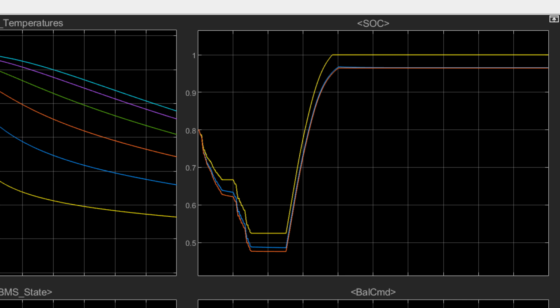The initial SOC in this simulation is 75%, but the SOC estimators were initialized to 80% to assess their capability to recover. It is apparent that Coulomb counting never does because it has no way to realize it is wrong due to the absence of voltage information.